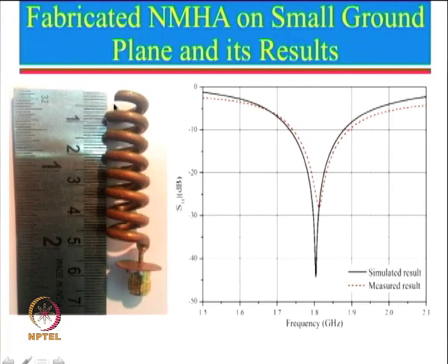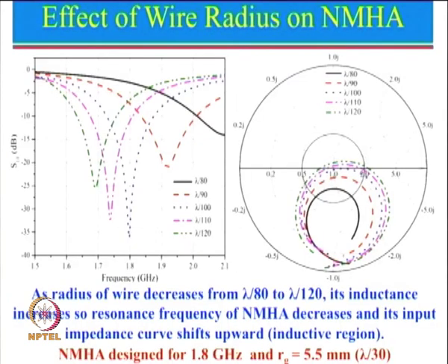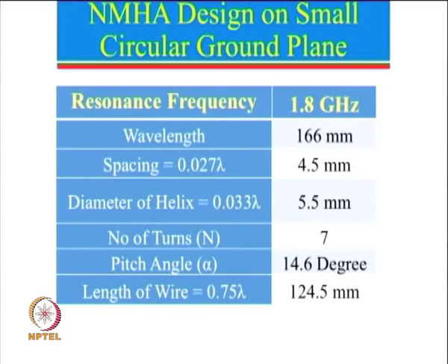So it is ideal for indoor application, and in some applications where we need circular polarization, I can just tell you that you take this diameter a little larger, you take C lambda a little larger, and in that case you will be able to design a circularly polarized antenna. We can actually go back and look into the slide if we want circularly polarized or other component.